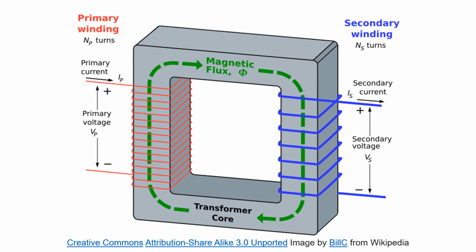But when an alternating current is applied to the same coil, there is significant impedance to current flow depending on the frequency of the alternating current, which is higher at higher frequencies than at the usual 50 Hz of the supply voltage. Diagram illustrates a transformer with two windings on a core.